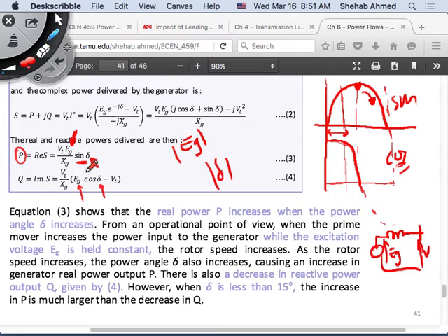Because everything we're talking about is happening in steady state, right? But what if Qatar Steel comes on board? A big load comes on board, and the delta changes. This is a physical system. At the end of the day, a generator is an LR circuit, like the one you took in 420. Put a step response on an LR circuit. What happens to the current? In steady state, L is a short circuit, and the current will go to its steady state value, right? How about the transient?